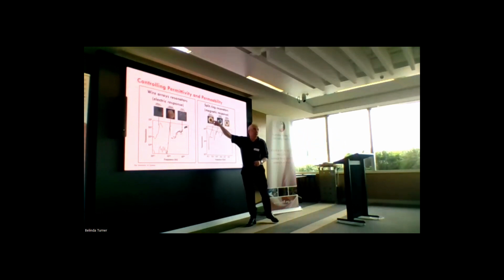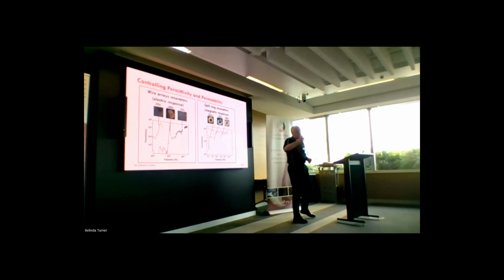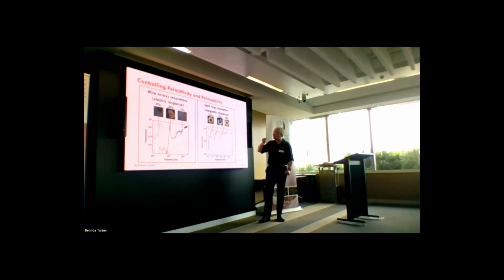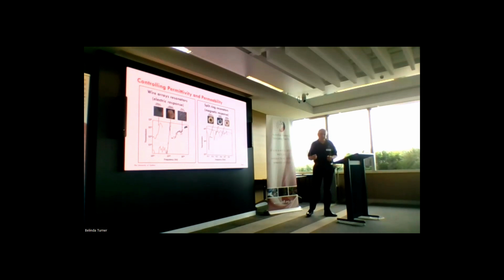You need to use a much more exotic structure. You've got to have some ring structure because the electromagnetic field has got to drive a circulating current. So we went to great lengths, rather than use wires, to make these split rings or split cylinders. Without going into much detail, we managed to tune the permeability from about -3 up to +4. So there's a way of using this approach for tuning those basic parameters. That's nice. We've modified some fundamental parameters, so we should do something with it.